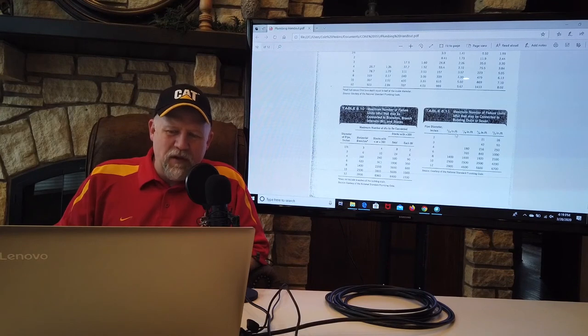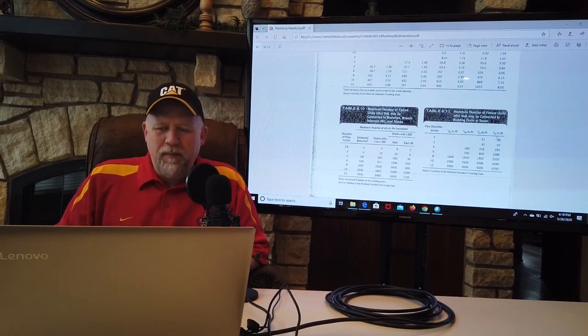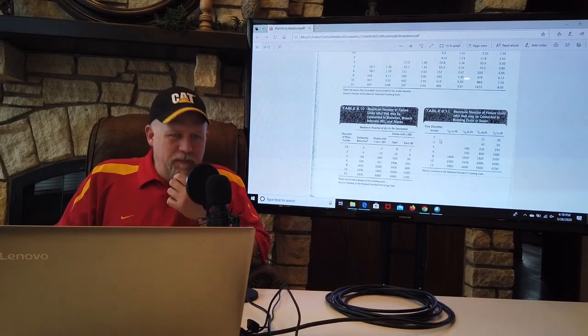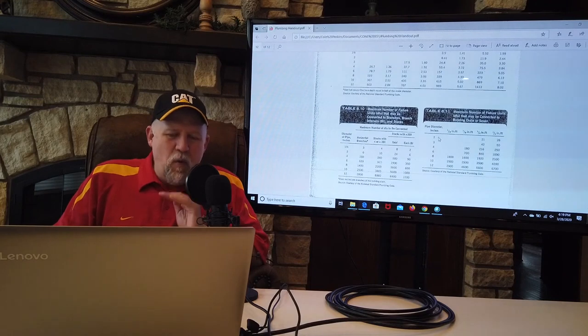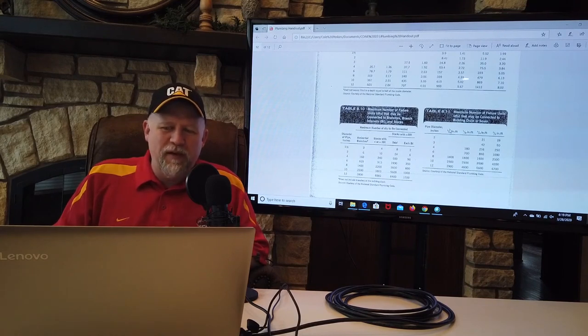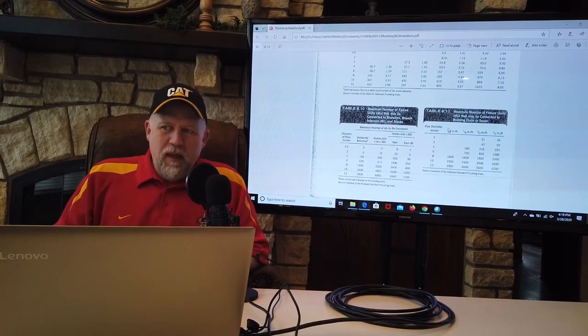And then you also have to look along the top, which is pipe slope. In other words, the force that gets the water and the sewage through a sewer pipe is slope. This is gravity drain piping.